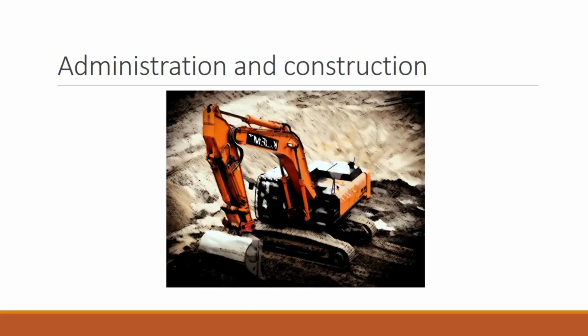And finally, moving on to the last subphase of stage 3, we have administration and construction. In this subphase, the contractors deploy to begin the project's construction after permits are obtained and bidders are chosen. Here, you need to make sure that there are temporary safeguards in place to protect surrounding places and unrelated employees. Temporary facilities like porta-johns and office trailers are frequently deployed at these sites. Posted signs for both deliveries and the owner staff are also deployed as well.